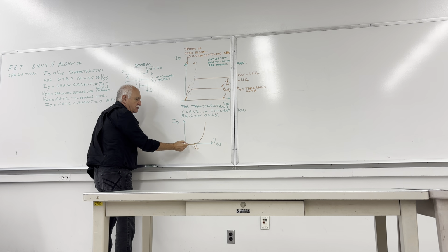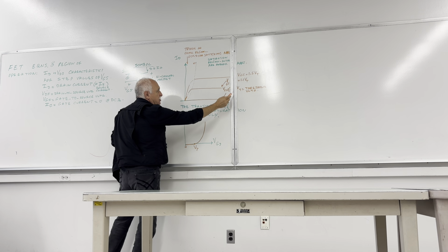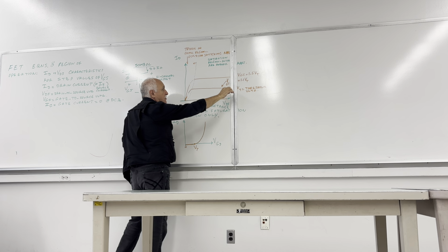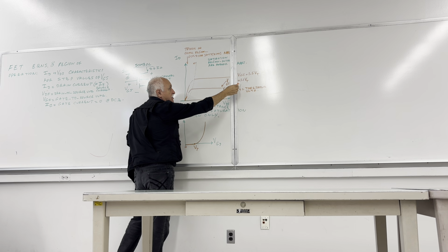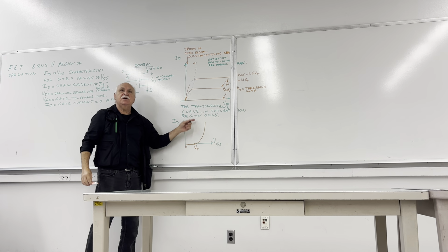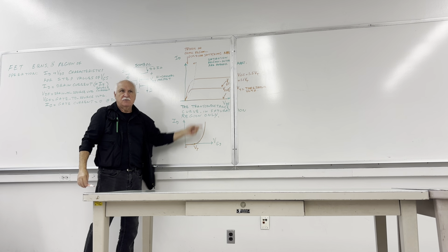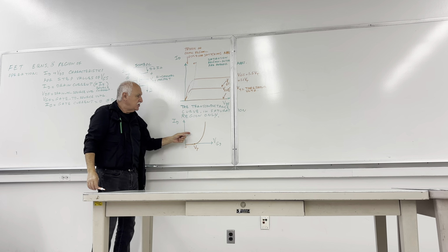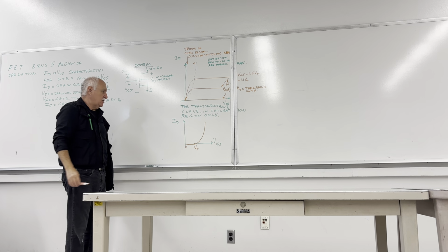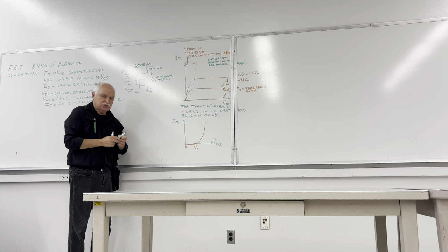So from 0 to the threshold voltage, there is no current. Here it is, that curve, lying on this axis. For VGS less than VT, there is no current. And then after you apply a VT, some percentage of VT, the current will pick up. The curve will be essentially a parabola to the nearest approximation. We are going to model them with equations in a minute. So this is called the transconductance curve, ID against the VGS, meaning ID is controlled by the VGS only, not with the VDS.